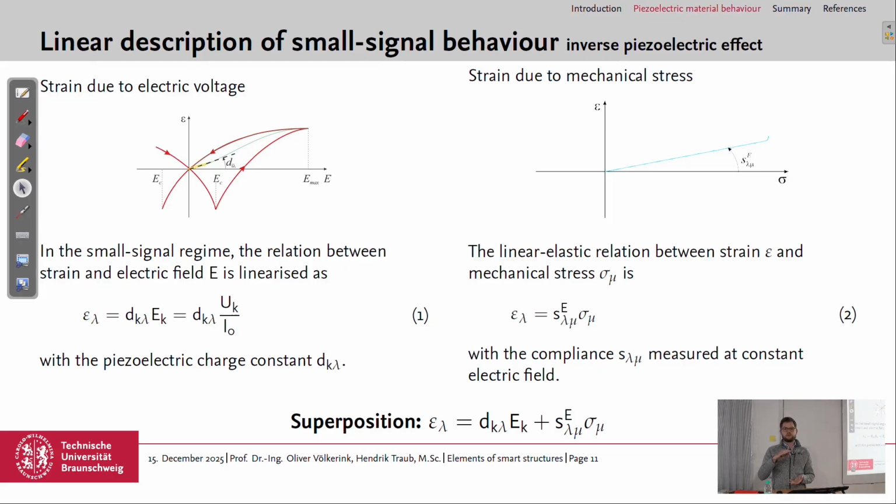So we measure the blocking force or the blocking stress due to the pushback of the force. But it's an external force we would apply to the piezoelectric material. But in free condition, there is none. Yeah, then in free condition this would be 0 here. We will have a look at that in a few slides. Maybe then it's clarified, hopefully.